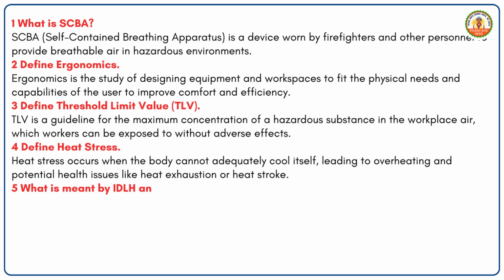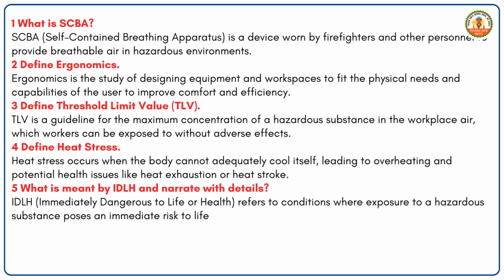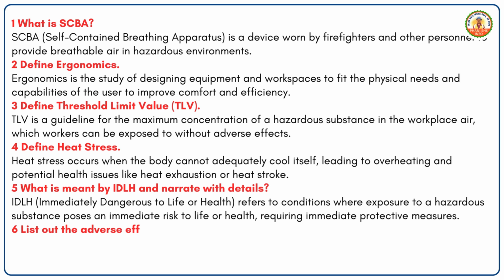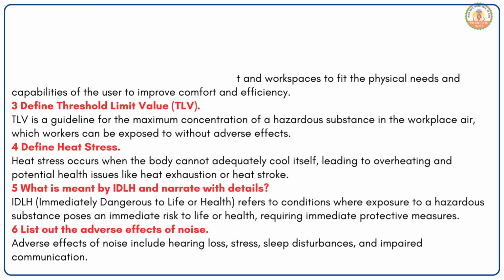5. What is meant by IDLH and narrate with details. IDLH, immediately dangerous to life or health, refers to conditions where exposure to a hazardous substance poses an immediate risk to life or health, requiring immediate protective measures. 6. List out the adverse effects of noise. Adverse effects of noise include hearing loss, stress, sleep disturbances, and impaired communication.